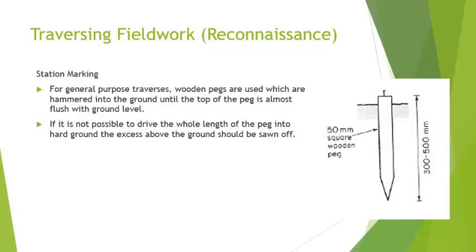And if it is hard to drive the whole length of the pegs, drive the pegs in as deep as possible but without breaking the top part, and cut it short. Similarly, leave approximately 1 inch from the ground. Make sure the pegs are firm enough and not easily taken off.